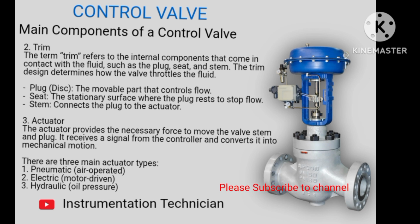3. Actuator. The actuator provides the necessary force to move the valve stem and plug. It receives a signal from the controller and converts it into mechanical motion. There are 3 main actuator types: pneumatic, air-operated; electric, motor-driven; hydraulic, oil pressure.